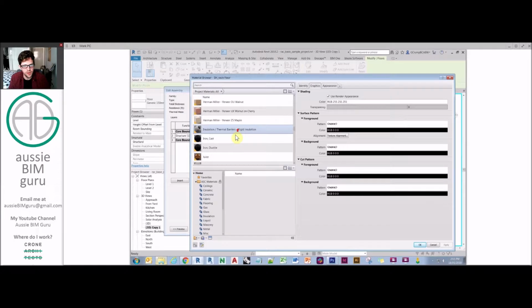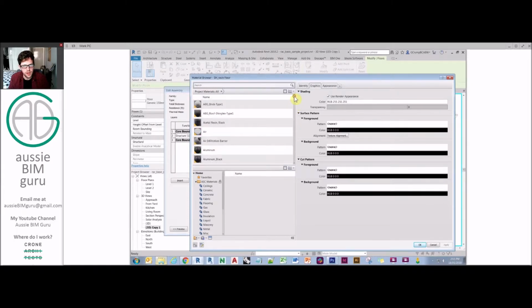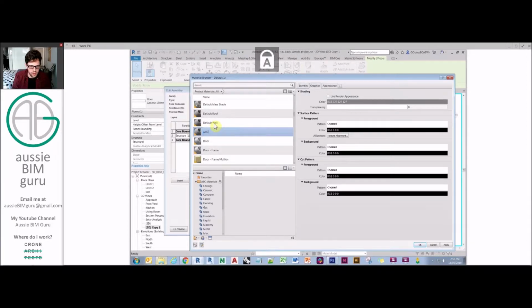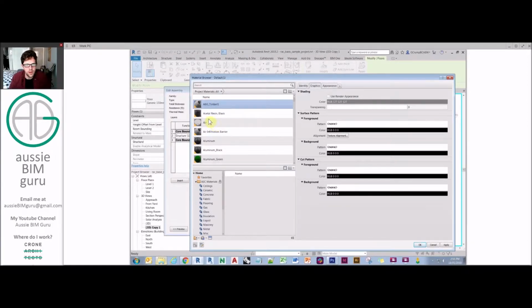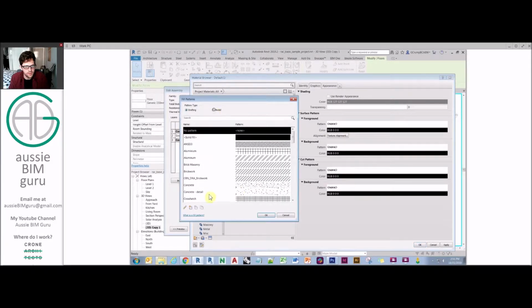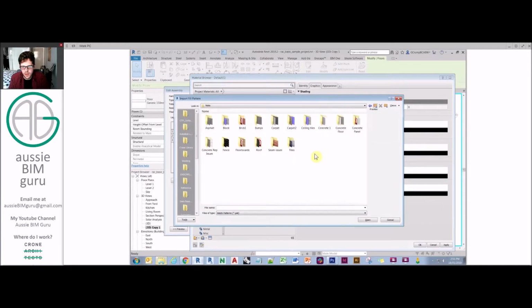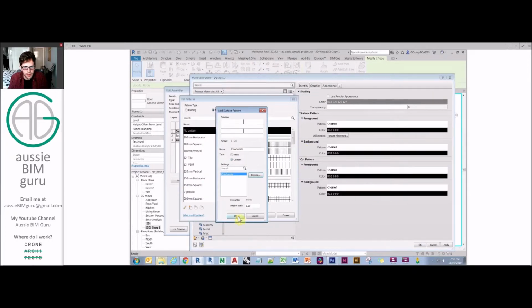We could start with a variety of different materials, but in this case we're going to start with our default material still, but we're going to use an asset that's different this time. We'll start with default and we'll just call this ABG Timber 1. Obviously you can pick more detailed material names if you so want. In this case we're going to pick a surface pattern as well. I do have a floorboard pattern that I've built for this application. I think it's 100 by 1800 with a staggered spacing. 180 by 1800, okay. So I'll just use that.